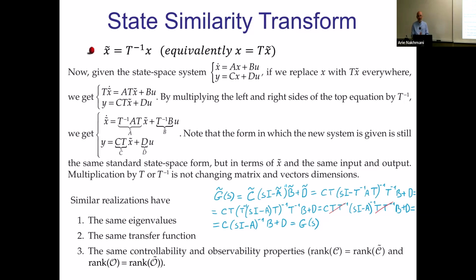The idea is that similar systems, which are defined that way, and you can define as many as you want, all of them will have exactly the same representation in frequency domain, which is the transfer function. Same impulse response, same differential equation, same everything, practically the same system. You just have a different representation for the same system, because all of the properties that we learned in control systems 1 were dependent only on the transfer function, okay?